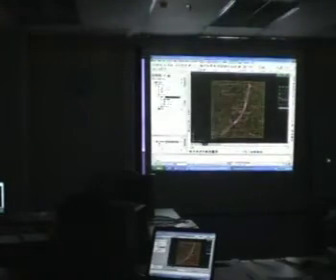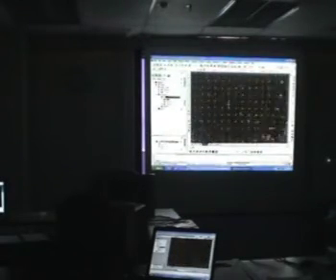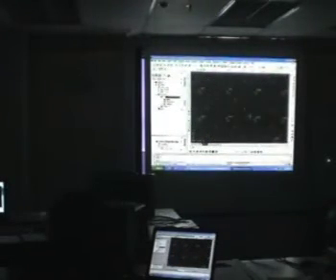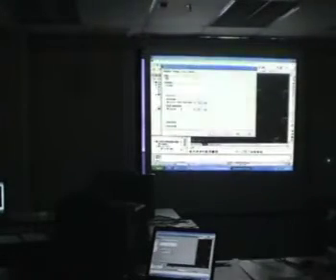I don't think you can see it, so I'm just going to zoom in so you can see the slope arrows that are coming about. Still being updated. Okay, these are the slope arrows. The slope arrows basically indicate how we are going downwards this way. So this is very different from Land Desktop. In Land Desktop, you've got to create all this yourself as you move along. With Civil 3D, no, you just set the settings and modify, and say, okay, instead of seeing the slope arrows, I want to see the points, you just apply. It will update for you.